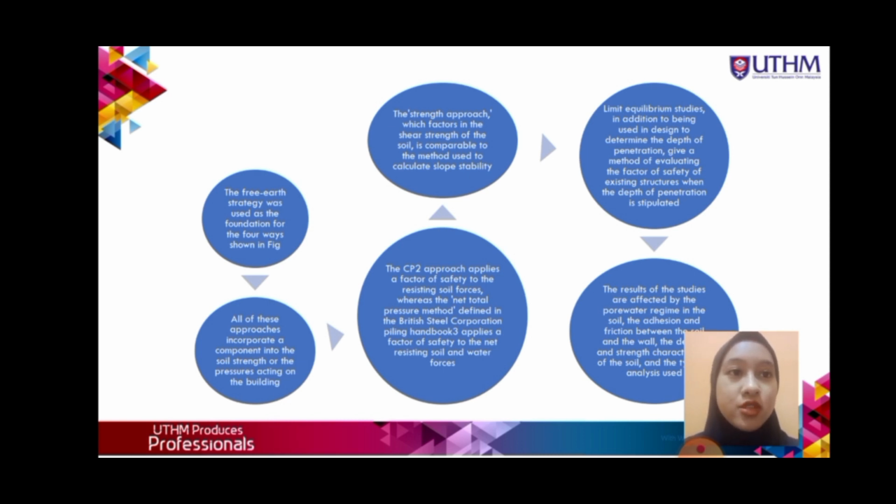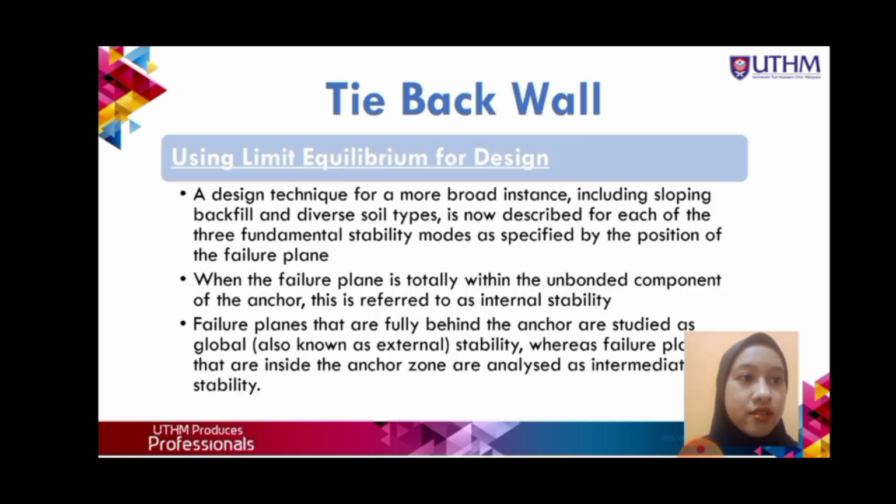Next, the strength approach, which factors in the shear strength of soil, is comparable to the method used to calculate slope stability. Limit equilibrium study, in addition to being used in design, determines the depth of penetration. And then the results of the study are affected by the regime in the soil.